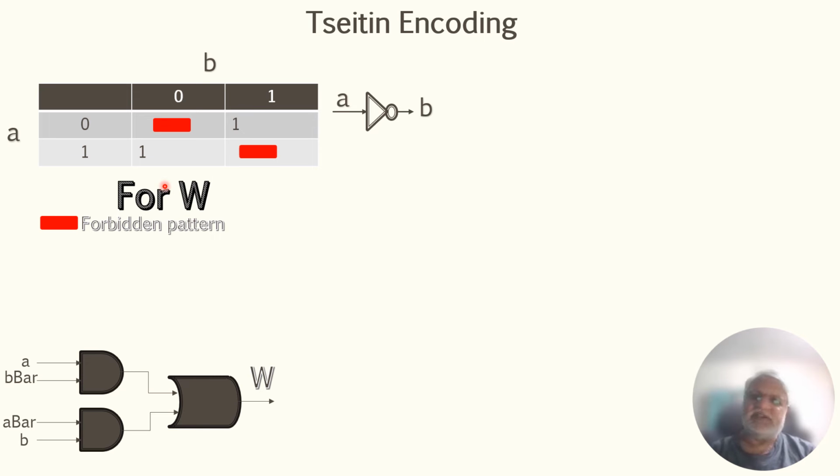We wanted to represent one equation based on inputs A and B. So this is slightly different. In Tseitin encoding, we not only take inputs, we'll also take output information, and we will represent both input and output in terms of CNF to represent how the gate will respond. So when that expression is evaluated and satisfaction is ensured, then we can say that the inputs and outputs are handled correctly, and we are getting the correct operation of the gate.